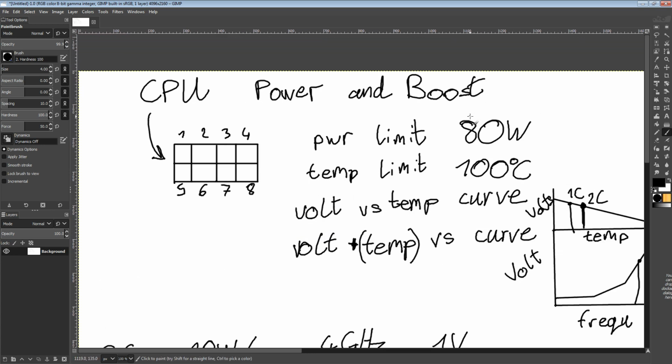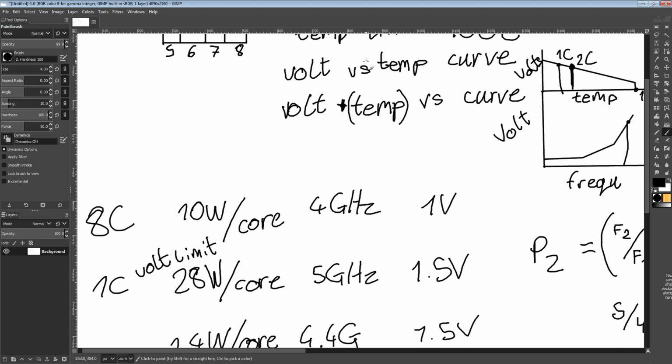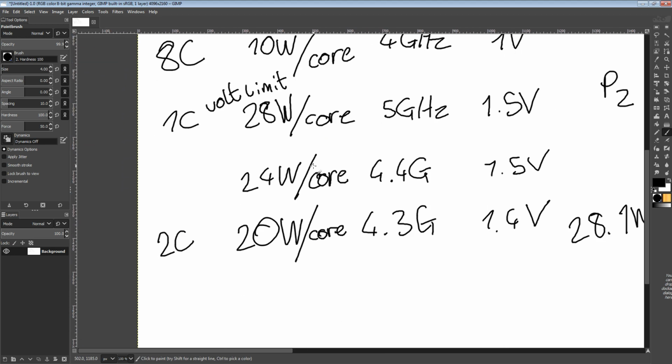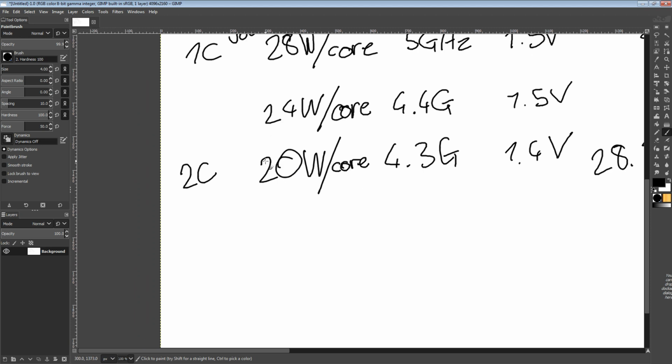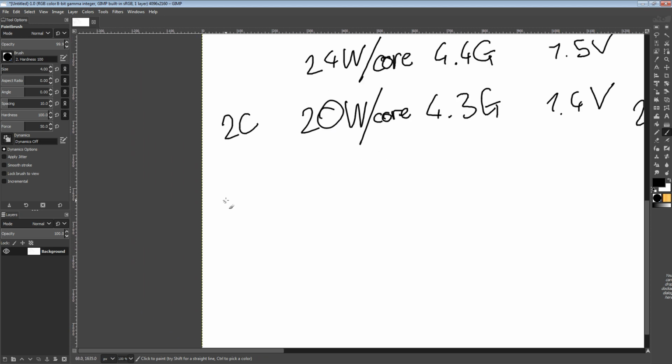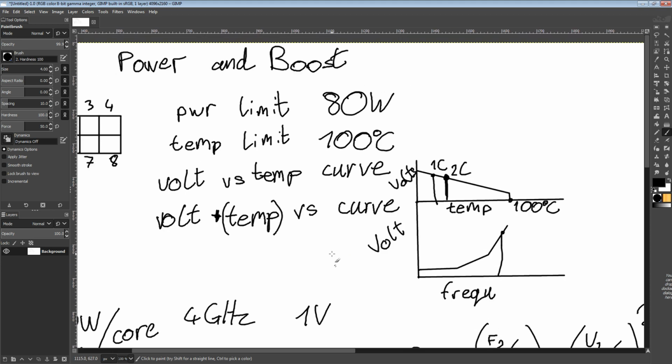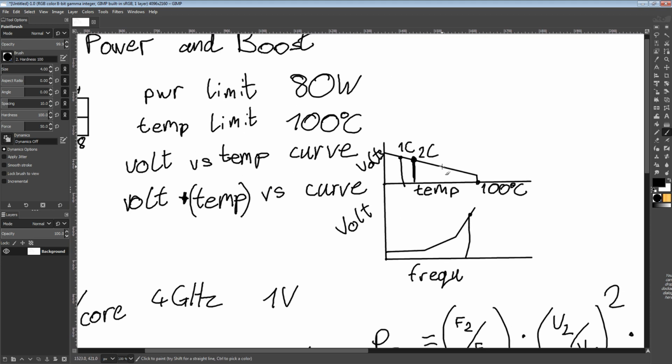And depending on your cooling system, 40 watts is nothing, but we're going to assume that we have an 80 watt heatsink. Okay, so 40 watts at this point starts being significant. 28 watts, not really. 40 kind of is. So that's that. Now, if we go up to a 4-core load, we could max out the TDP and run 20 watts per core, but we'd really quickly just slam into the temperature limit, so we're going to end up maybe here for the 4C.